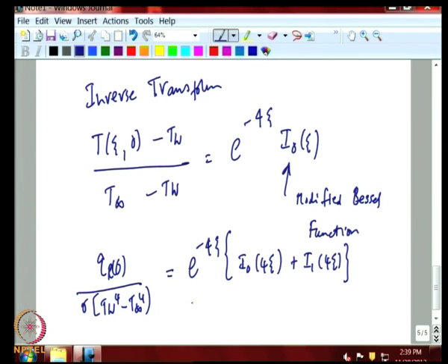Now, if you want to understand what this psi is, it can be rewritten in terms of the conduction radiation parameter which we discussed earlier, the length scale, and what is known as Peclet number in convective transfer. N is an expression where N we have already defined as A into k by 4 sigma T infinity cube, which came up in the conduction radiation problem, k the conductivity, and Peclet number is nothing but u infinity x by alpha.